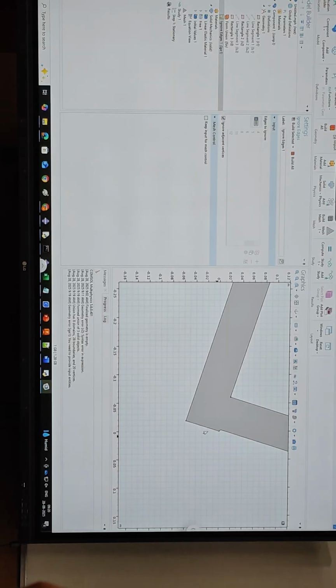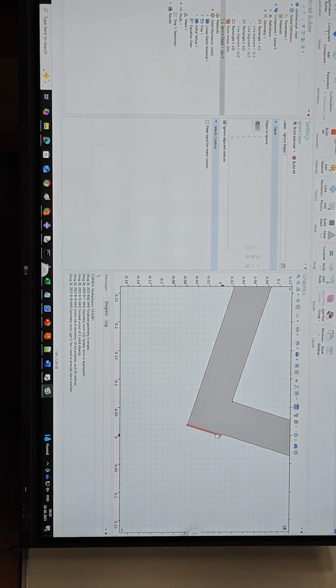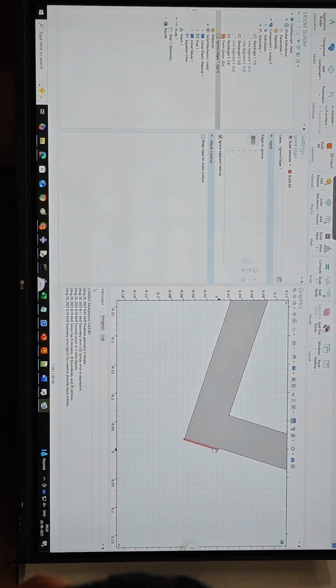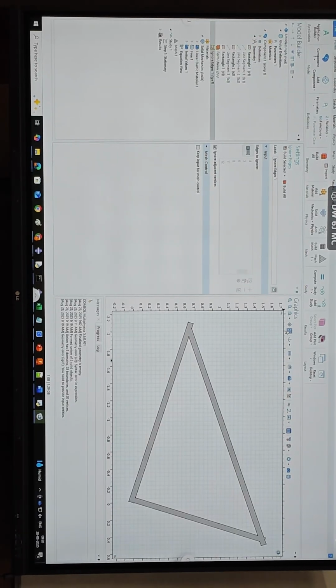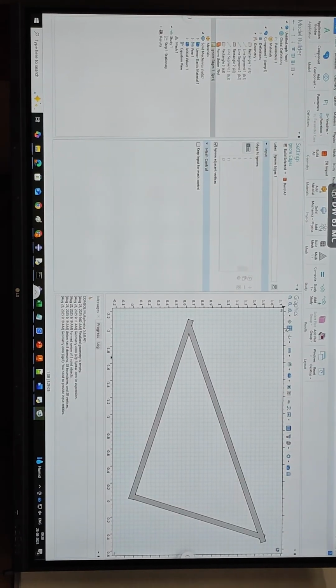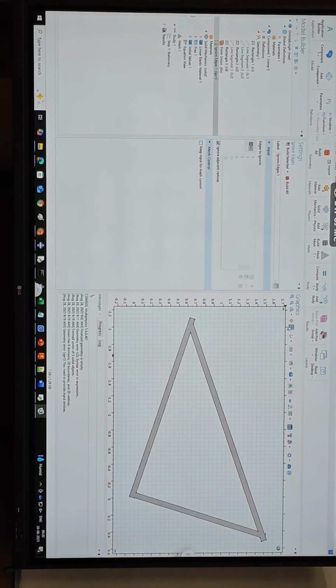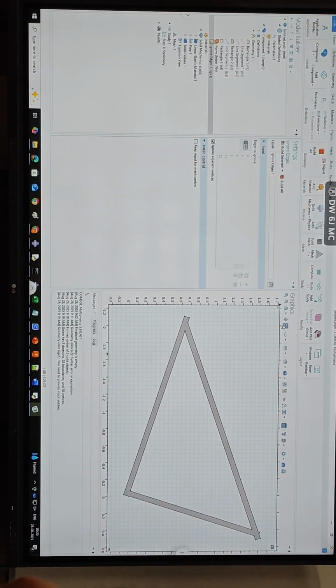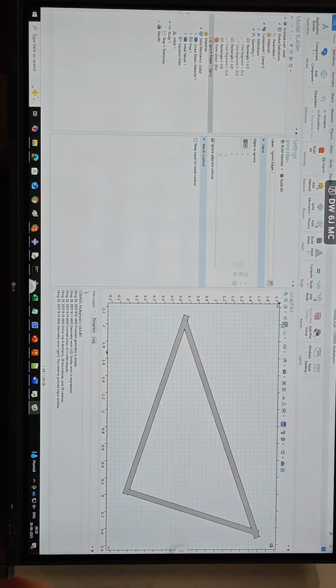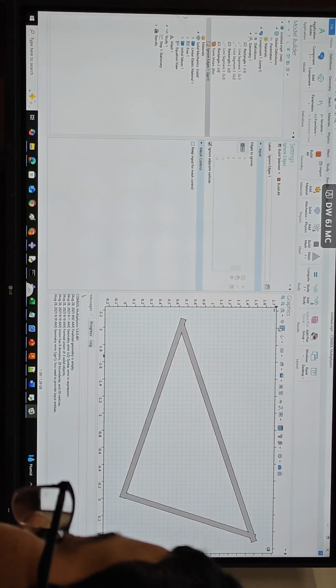If you perfect your arrangement, you will not have these little bumps here. Because we'll be using an adaptive mesh technique, you'll get a little fine mesh around here because of this notch. Now if you look at the structure, you have the connections made without these intersections. So you won't have too much adaptive meshing at the connections because there are no more intersecting lines. But you'll definitely have it at the corners.